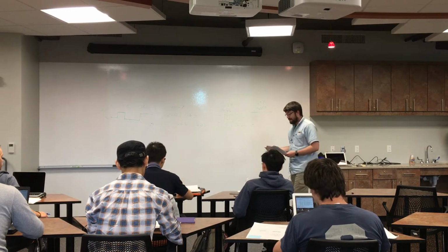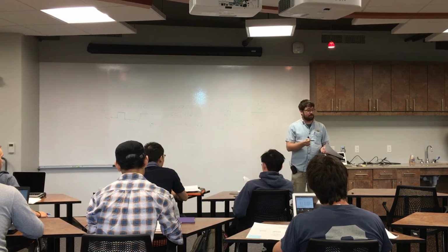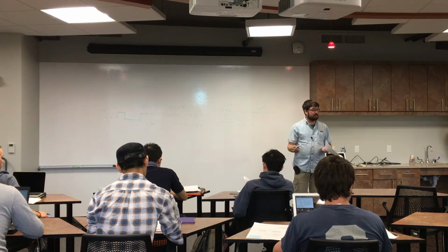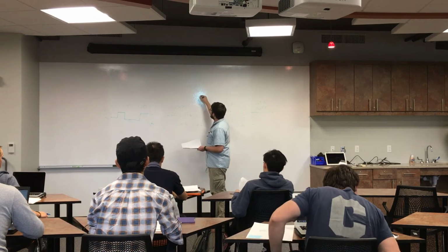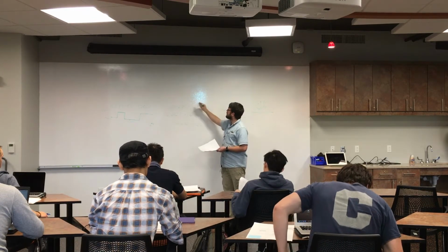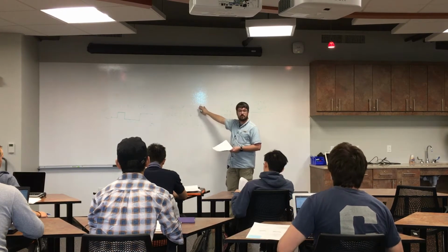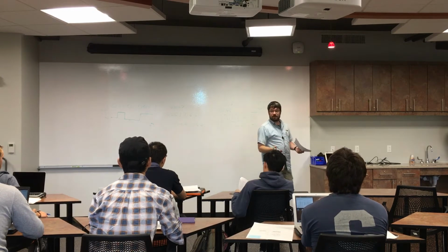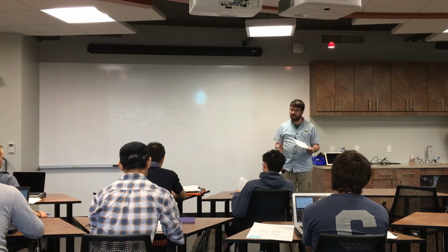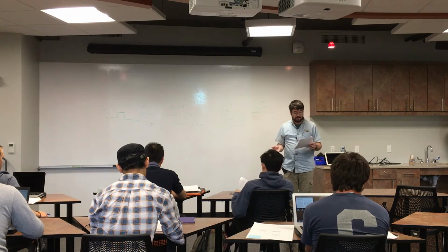A few things that I had in mind when I wrote the question would be things like multiply floating point numbers so that they're integers for the part that you care about. Like we talked about, if you had a temperature of 25.6, well, you could multiply it by 10, so you have the number 256, and you can do just integer operations on that. That would be one way. There is a floating point library, though I don't recommend it unless you really need it. So you could use libraries. Some people wrote that. You could do some binary math.